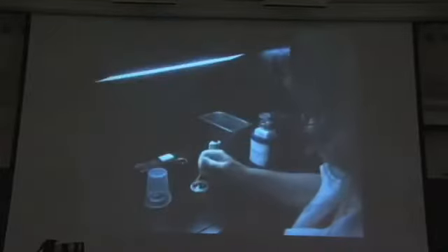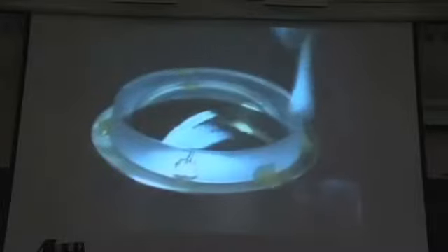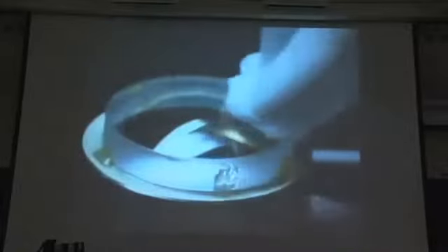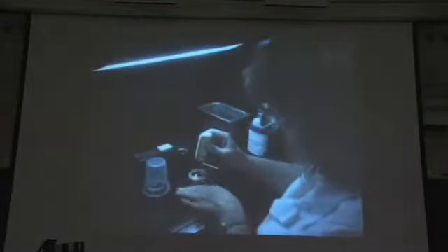They give the lens another cleaning. Each one must be absolutely spotless before they proceed to the next step. Otherwise, dust particles could become trapped within the optical system and affect image quality. Now that the surface of the convex lens is immaculate, she dabs optical cement onto the center of it.